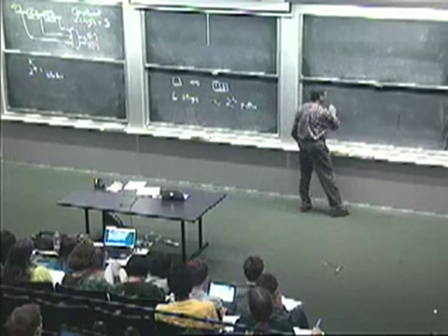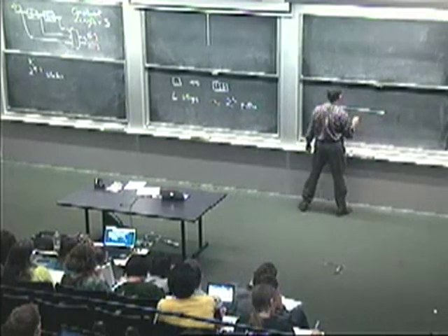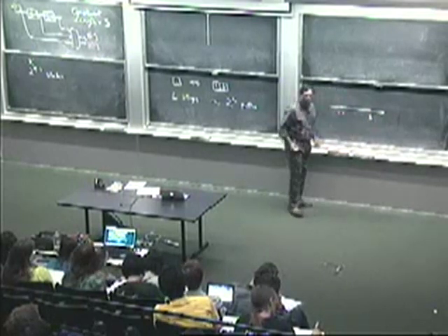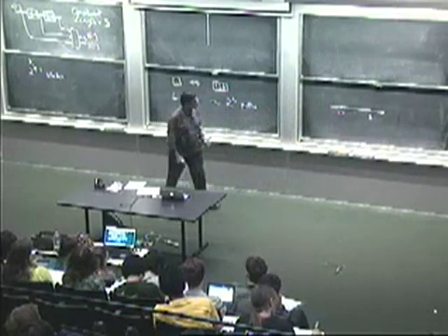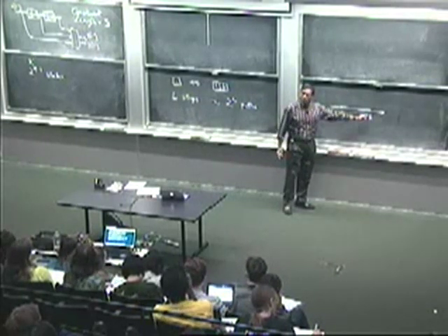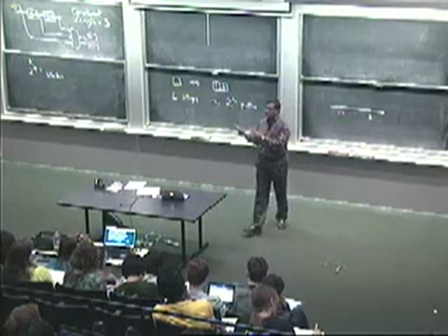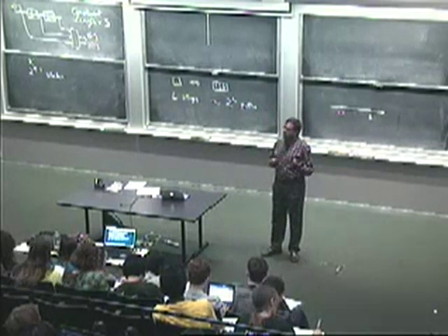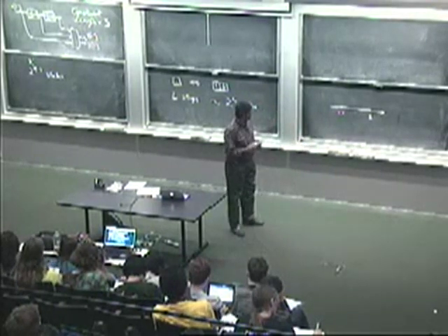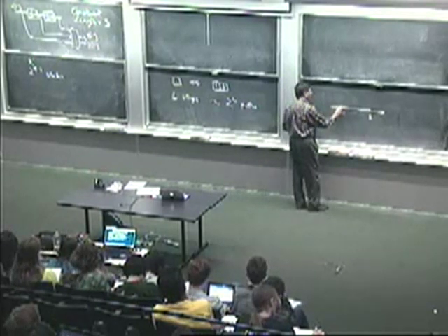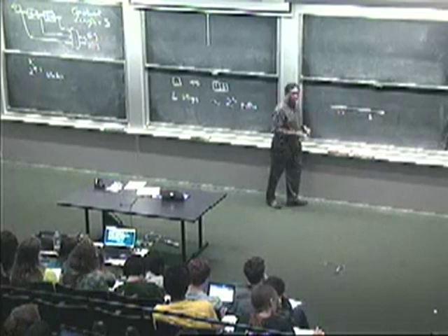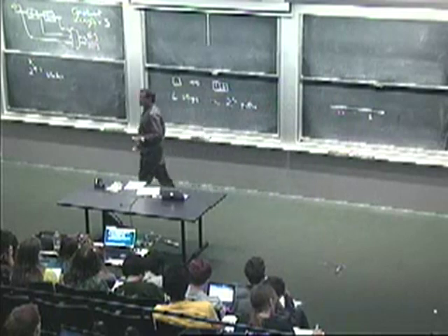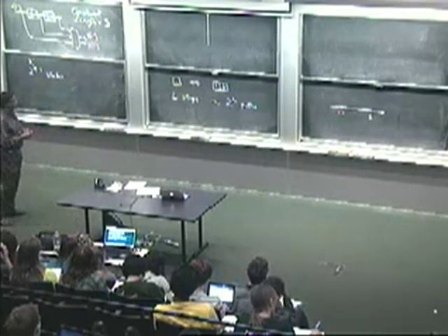So if I was to draw this on the real axis, thinking of a voltage, we've got 0 volts that we're expecting, 1 volt or something proportional to 1 volt that we're expecting. These are the 2 possible values depending on whether a 0 is sent or a 1 is sent. This is because we've coded the bits at the transmitter for physical transmission on a continuous time channel. And then at the receiving end, we're doing some processing and extracting samples, right? But because of noise, you get samples anywhere around the 0 or anywhere around the 1, depending on the particular transmission instance. So it'll vary from one instant to the next.